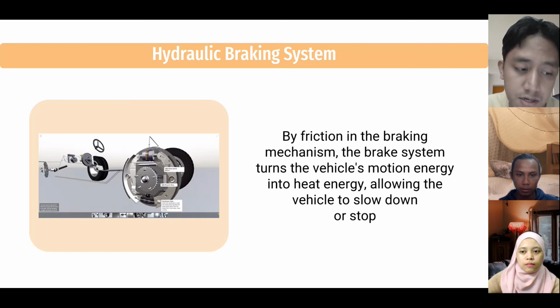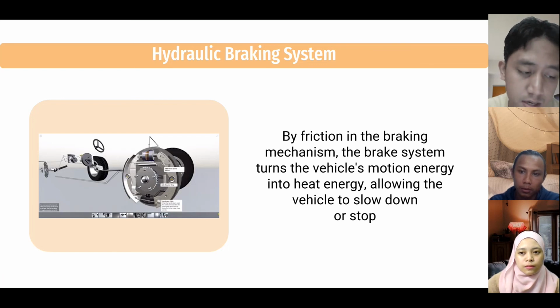It increases the force generated in the brake pedal using the Pascal principle and transmits it to the wheel cylinder. It also converts the small pushing force created by the driver's foot on the brake pedal into a friction force, so that it can easily stop the vehicle with the pads.